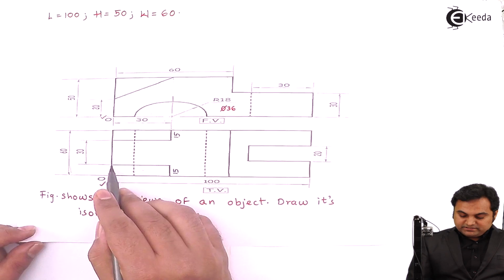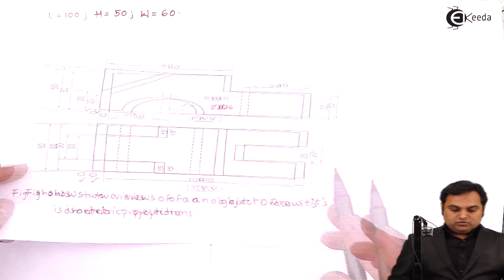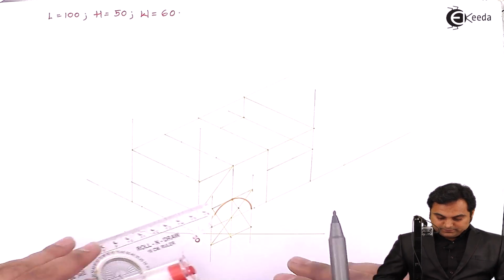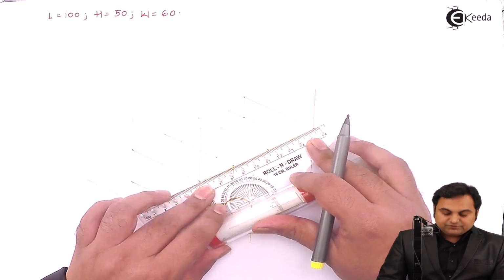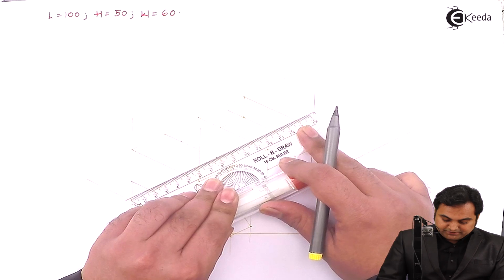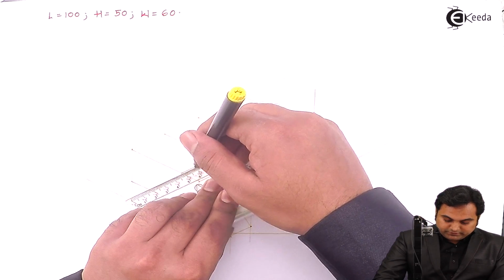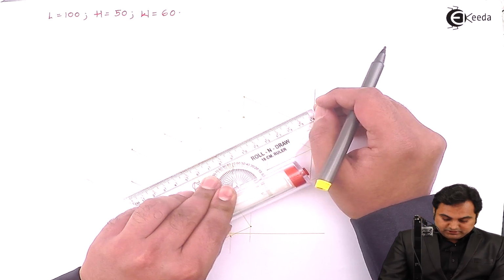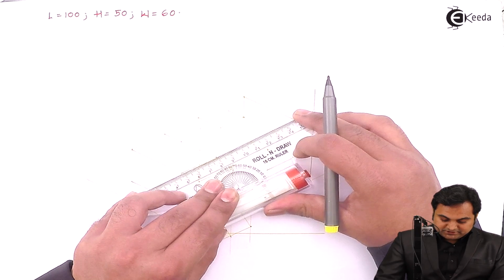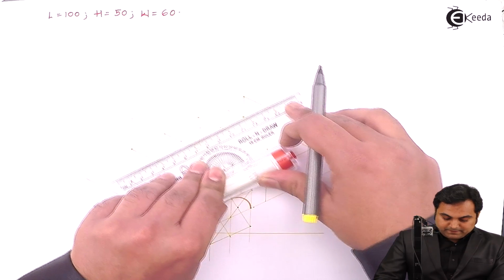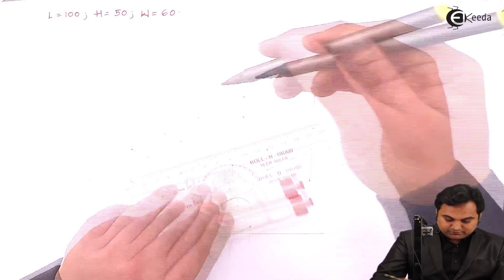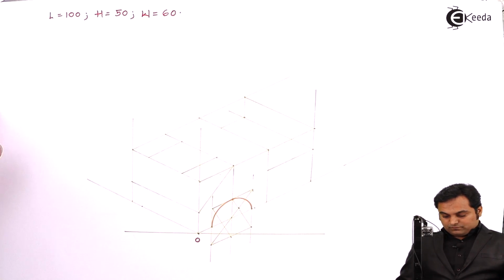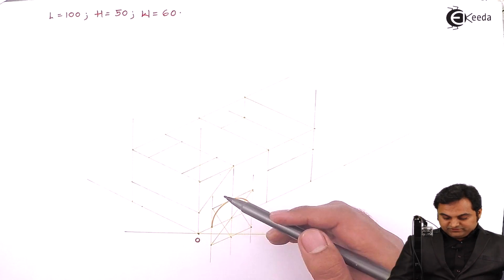there behind is a straight horizontal surface. So for that, I am measuring a line parallel to the length, projecting it behind, getting that surface. Similarly, I am keeping this line parallel through this point. I am drawing a light horizontal line. And then I am going to complete these surfaces.